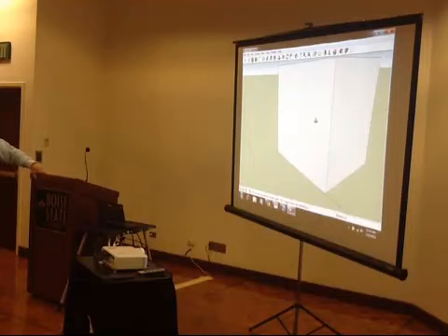Sorry to interrupt. So, has everyone then clicked with push and pull, and then before you click again, typed the numbers, hit enter, and we have extruded to a height.